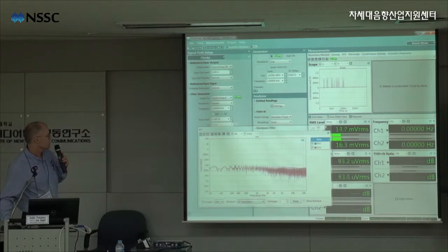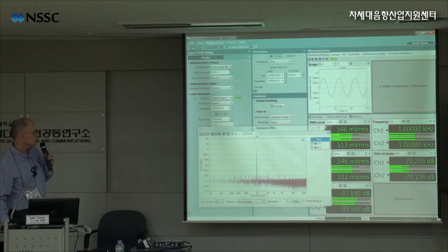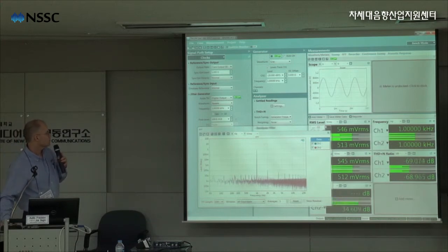Try backing down the amplitude or the peak level of the jitter. Yeah, there we go. So at 100 milli UI, or a tenth of a UI, we're getting some signal with the square wave jitter. But you can see a lot of these harmonic components coming in. So the device really does not tolerate square wave jitter very well at all.